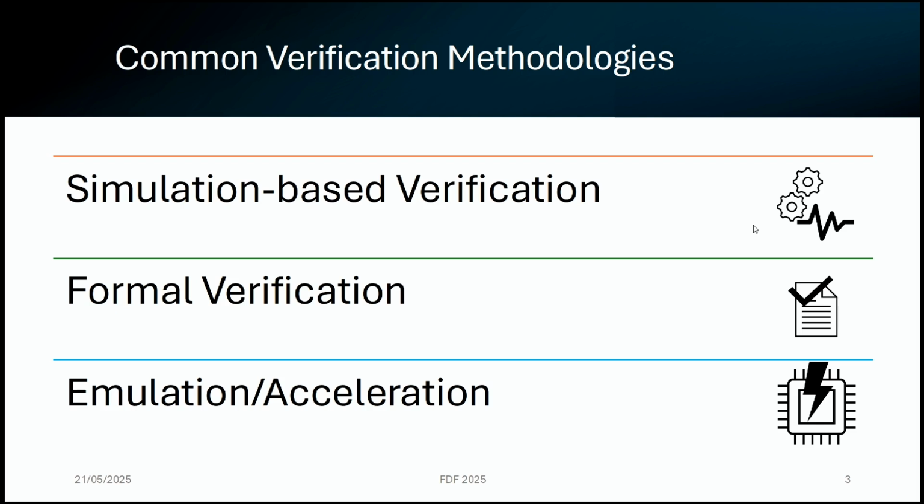So, common verification methodologies. Hopefully most of you are at least familiar with simulation-based verification. This is quite a common way to do verification, not because it's simple, but because it's pretty available. Usually that's based on the concept of building a test bench around your design. What you really do is write a piece of software made of components that you use to drive and monitor signals. Then you need to write some stimulus, some checkers, and hopefully some coverage. Then you put everything into your simulator and you run it.